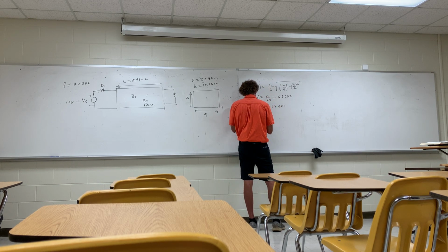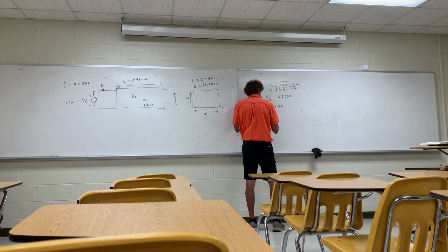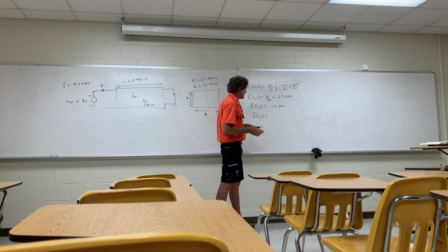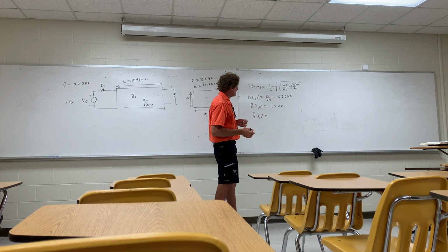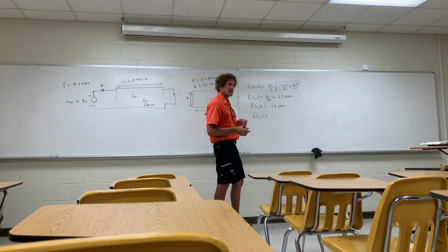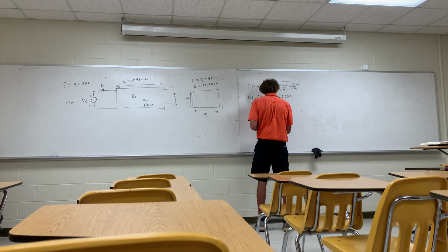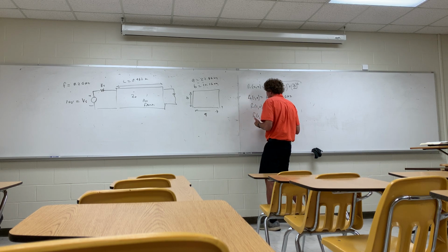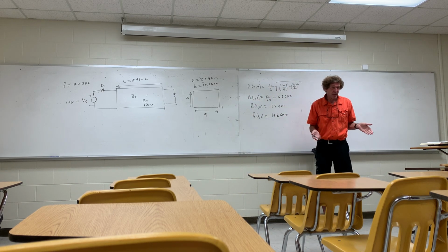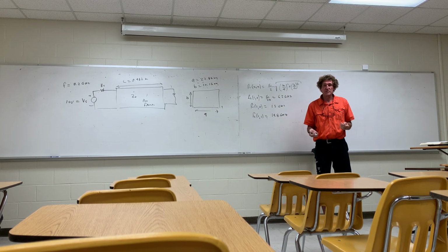And then the next mode is FC11. And that's going to be what, 15, 16, something? I can't tell. It's m and n equal 1. We're slightly higher. What is it? 14.8. Is that it? That sounds about right. 14.8 gigahertz. All right, so these are the first 3 lowest order modes, in case you're asked that, right? The lowest frequencies that propagate.